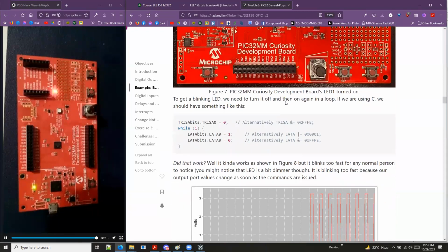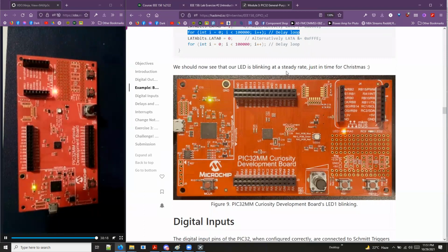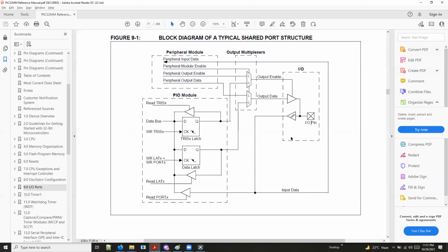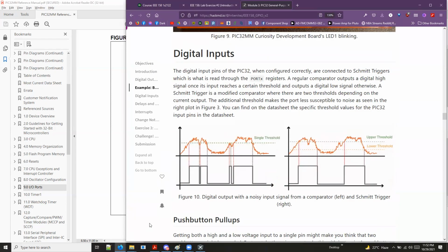digital output. So here we go to the more complicated digital inputs. Our digital inputs, if you recall our block diagram, have a Schmitt trigger here. A Schmitt trigger is basically a glorified comparator, or I mean, a comparator that is more noise tolerant. So a normal comparator basically compares, hence comparator, two signals. Usually the reference is placed on the minus port, and then plus is our signal.